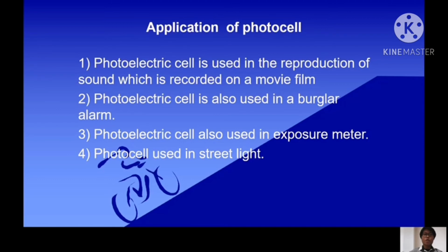Last but not least, photocell detects if the light is needed. Photocell is used in the street light. Photocells are light-sensitive sensors that respond to the amount of light detected. When the light is too low, such as at dusk or under heavy overcast sky, the sensor tells the computing unit within the street light to activate the flow of electricity. When the photocell detects too much light, the sensor will deactivate the street light.